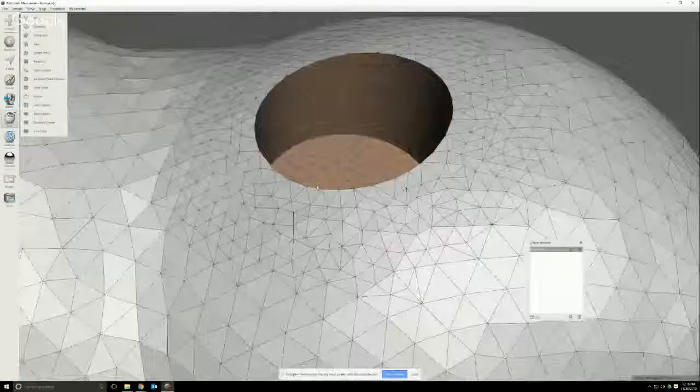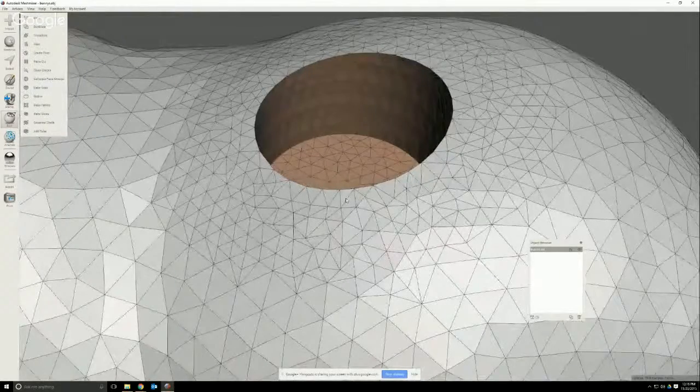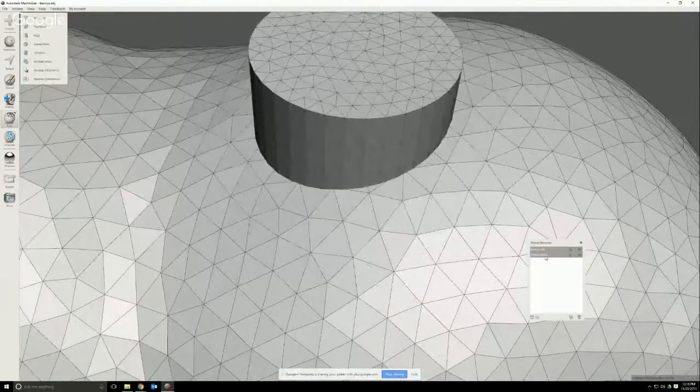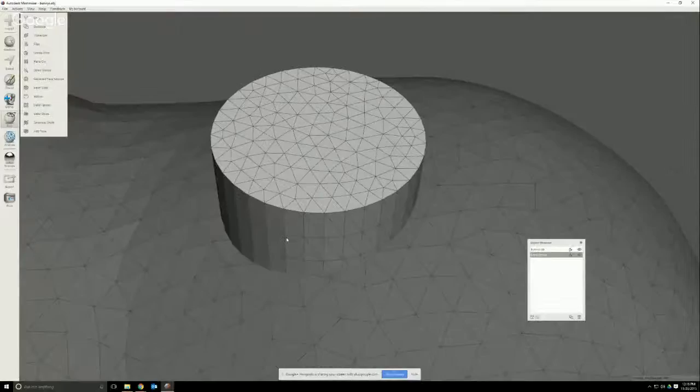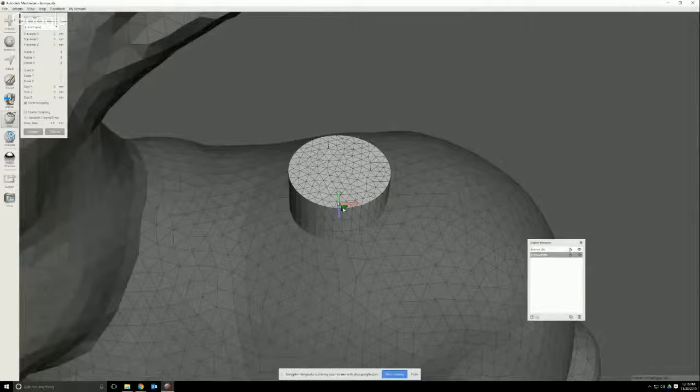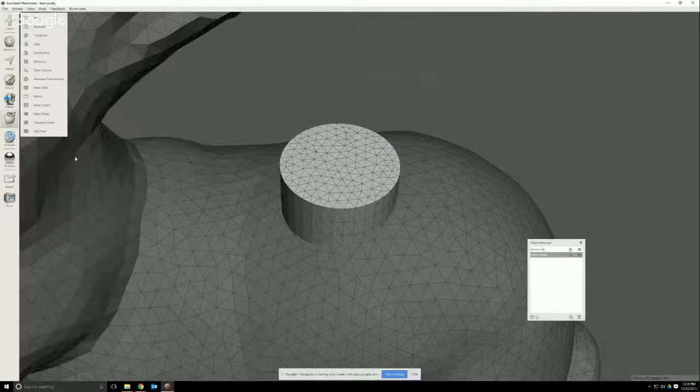But if I want to go back in and change this to 7 millimeters, I would have to undo these. I could try to undo these. Now that I have a 6 millimeter cylinder, I would have to hit the T key for transform. And I could try to scale this up. Actually, I could just type it in here to 7 millimeters and click accept.